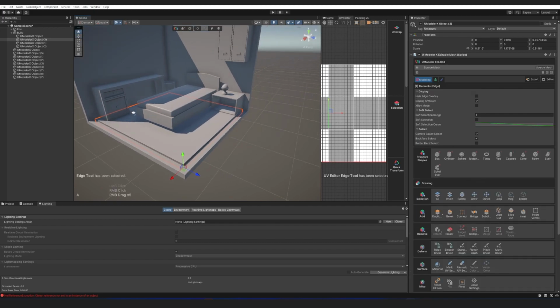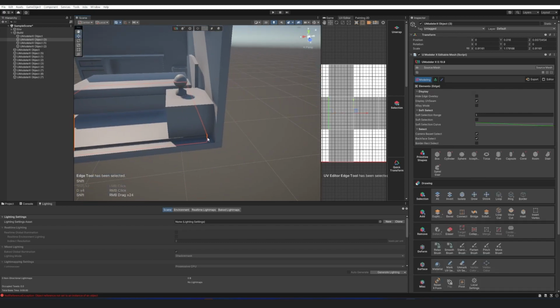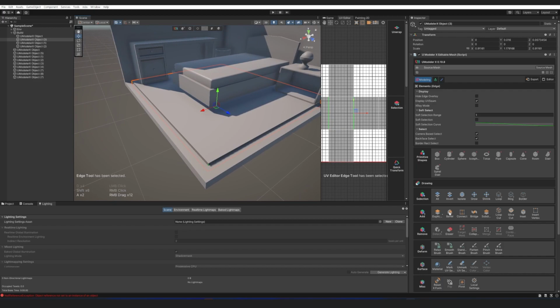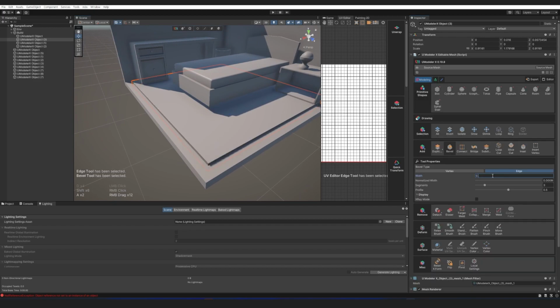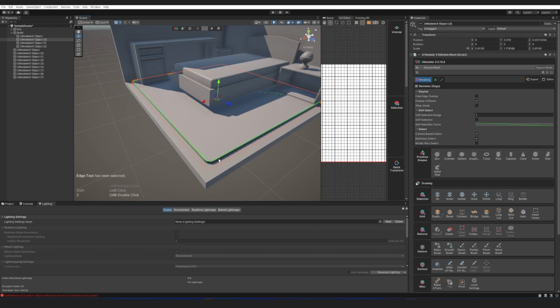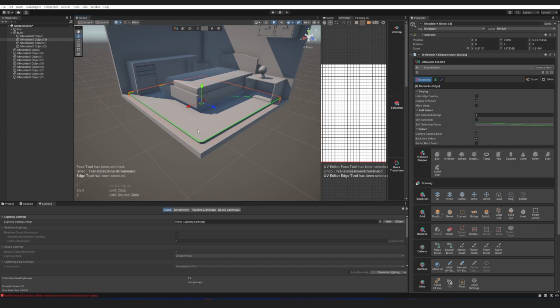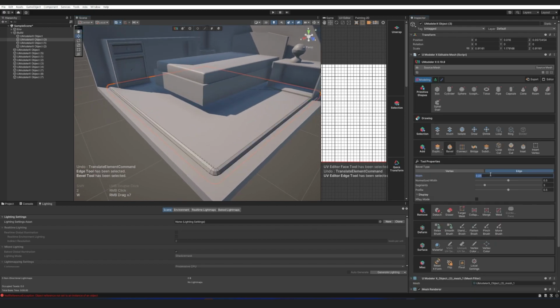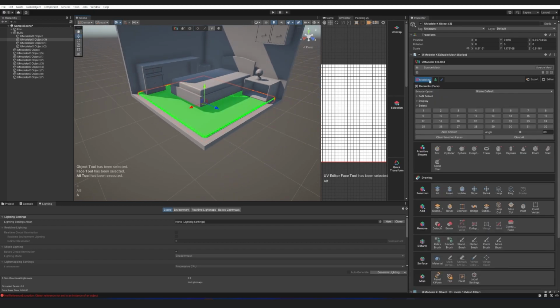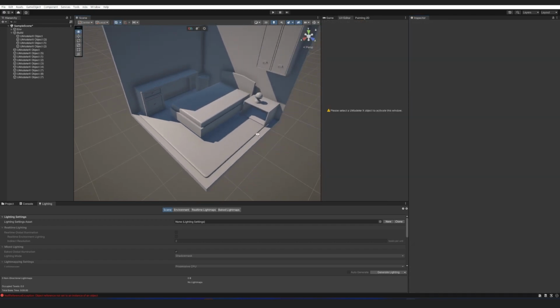Raise the duplicated object and reduce its size. Then, select the rectangular edge and use the bevel function to transform its shape. When using the bevel function, adjust the values on the right finely and use the preview to set the bevel value. The carpet creation is complete.